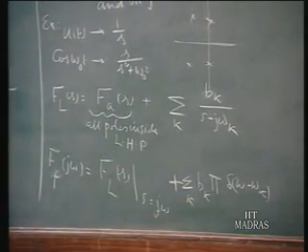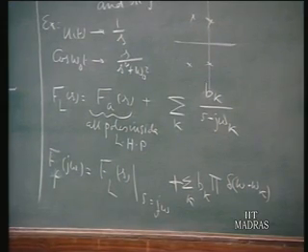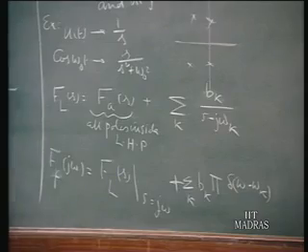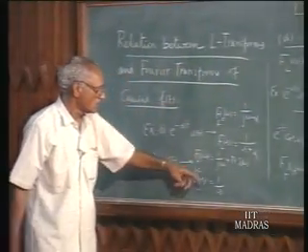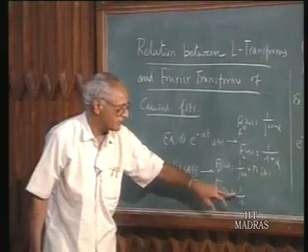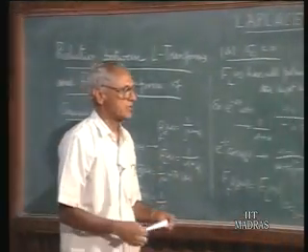So it turns out that in such situations, for every pole on the imaginary axis and the corresponding residue, you have an extra delta function, and that is why for u(t), 1 over j omega, you are getting pi delta(omega). The corresponding residue here is 1, so pi delta(omega) you are getting. So this is what it will be.